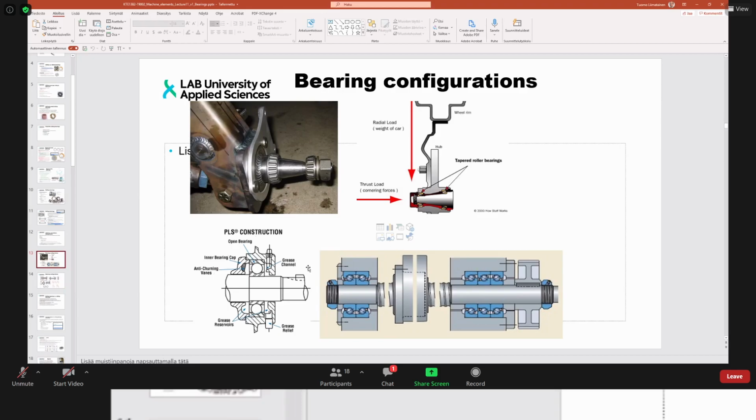In here you can see a bearing system which contains only half of it. There's one deep groove ball bearing, and there are some cavities which can contain grease and also guide the grease away from the bearing system. And this bearing, in this case, is open, which means that there are no seals on the sides of the bearing, so when we feed lubrication grease from here, it can freely enter inside the bearing. And then, of course, used grease can eject from here, from the grease relief.